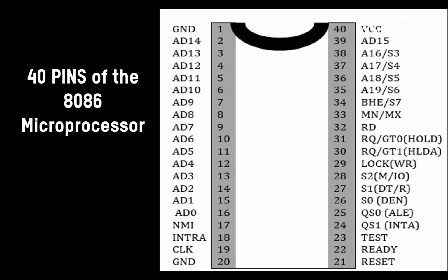Let's start. The 8086 microprocessor is available in different clock rates and packaged in a 40-pin configuration. The 8086 operates in single processor or multiprocessor configuration to achieve high performance. The pins serve a particular function in minimum mode, single processor mode, and other functions in maximum mode configuration, multiprocessor mode. The 8086 signals can be categorized in three groups.